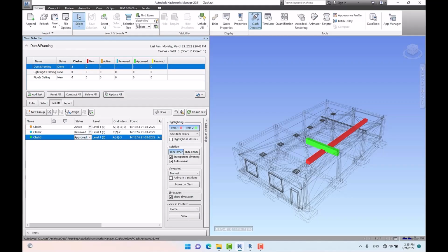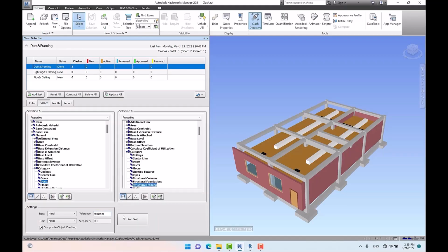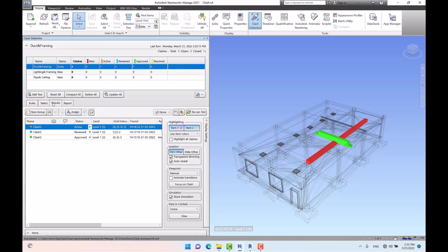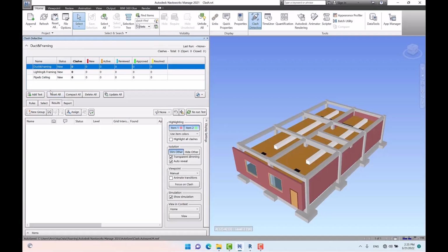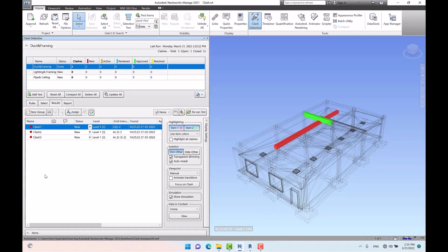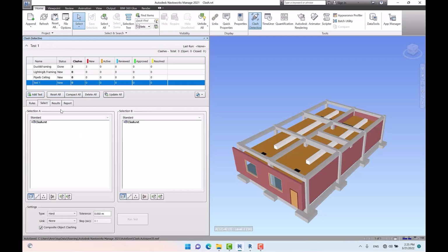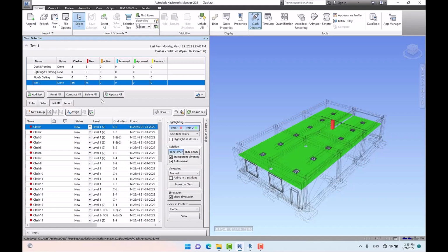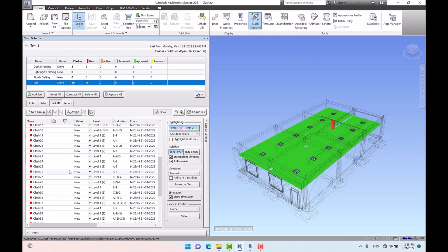I rerun the test, then I reset the test this way. Here a small point is left, and I am obliged to mention it, which is the arrangement of the clashes, or just setting them in order. But before that, let me run a test as a sample, in which we get a high number of clashes in the results, and then I want to elaborate on it. Note that it is not normal to set up the same files against each other in the test criteria. Let me run the test. Following that, I'm going to arrange these 46 clashes. Don't forget that it's just an example.